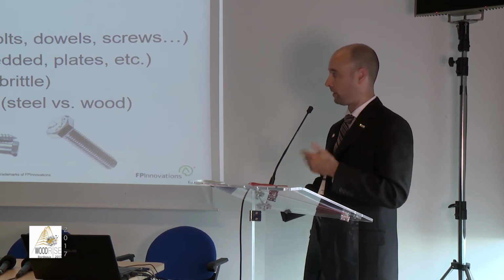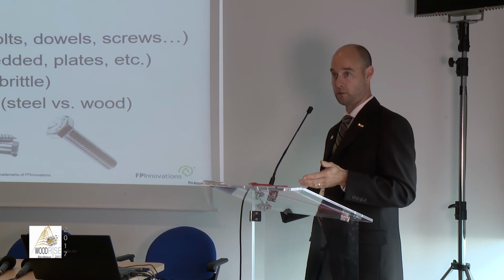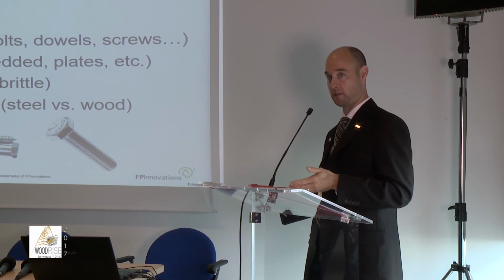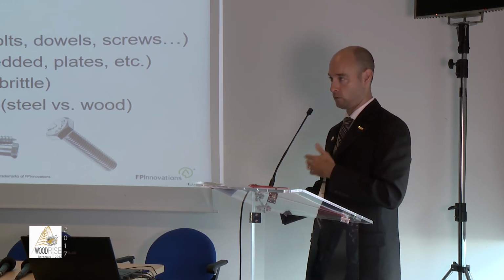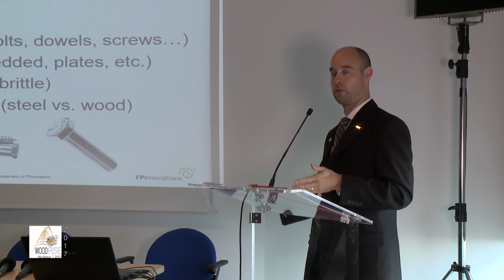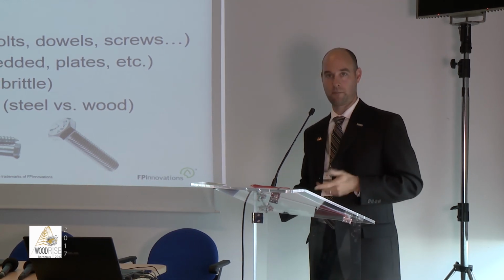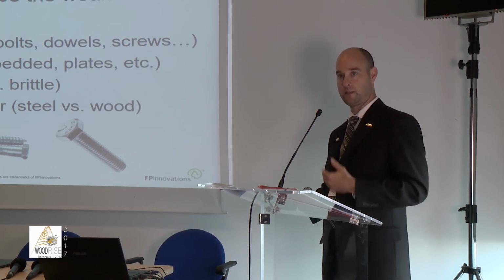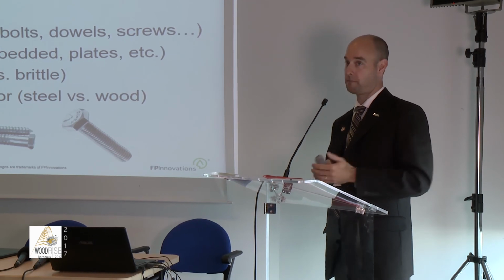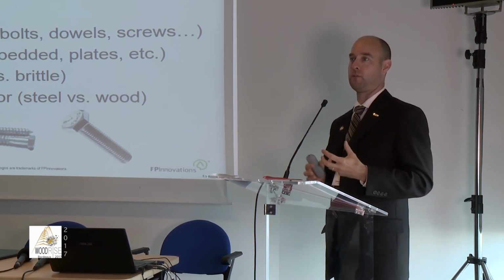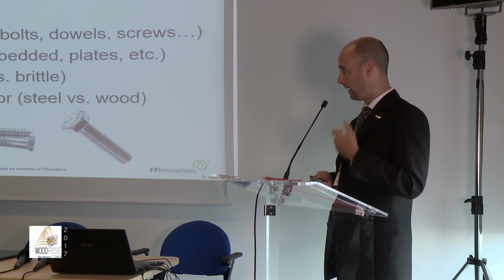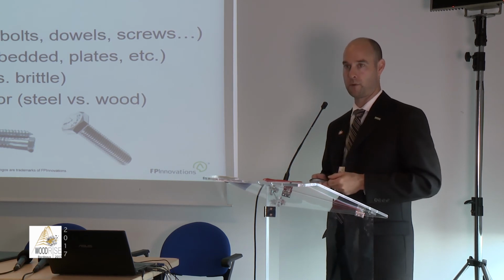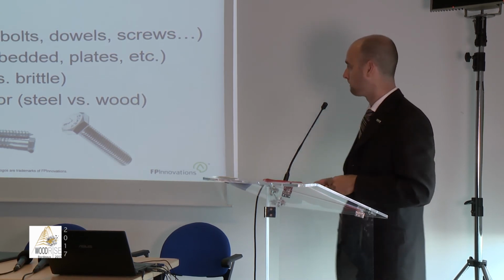So connections are complex. The structural engineers who do connection design know that it is not the easiest part in a concept. We have a wide variety of fasteners, whether it's screws, bolts, dowels, drift pins, whatever. We have different configurations as well: exposed steel plates, internal seat plates, hangers. So there's many factors that need to be thought of, and there's a lot of testing still going on, and we'll have some more hopefully in the soon future.